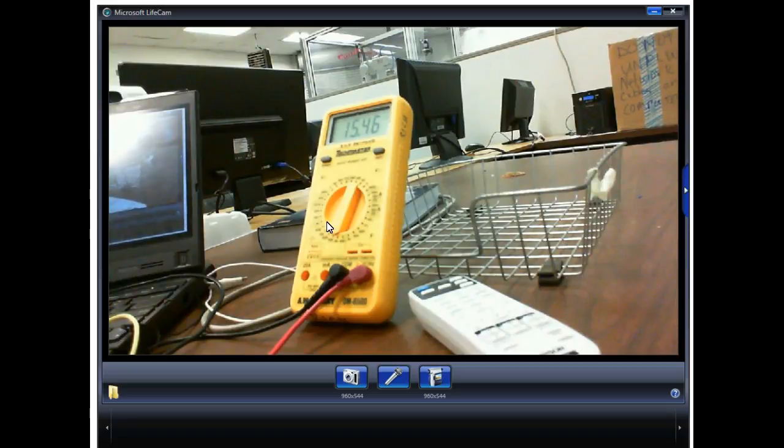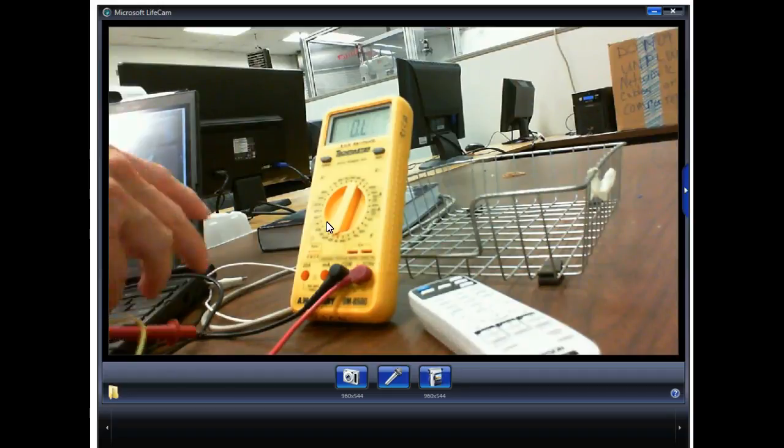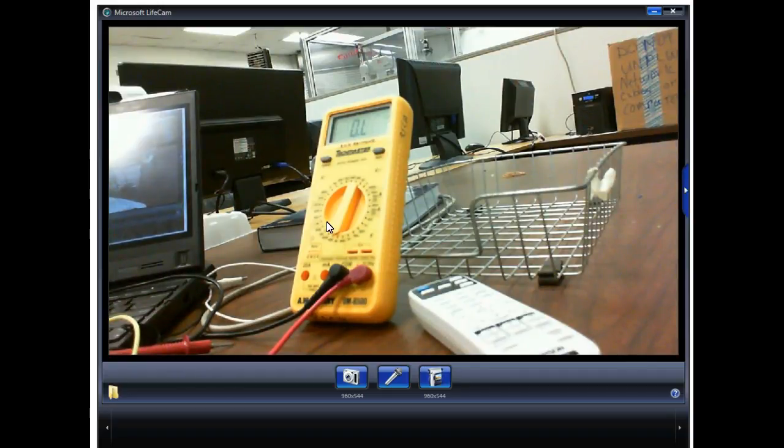Our gain is going to be a little higher than before, because we were using 13.2K to calculate it. Here we actually measured 15.46. So we can take 15.46 and divide it by 500, and that should be our power gain.